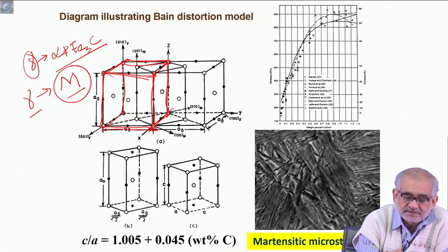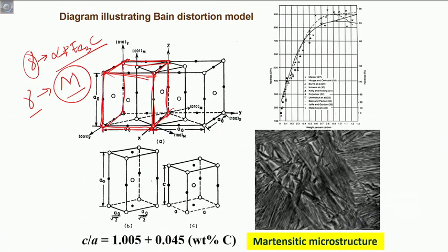But now, if this unit cell, because of very large compulsion and no time given, suddenly is forced to change and take up a new unit cell, the possibility exists whereby you now have to consider these 4 atoms on the top plane, these 4 atoms at the bottom plane, and one more at the center, which earlier was the face centering position.